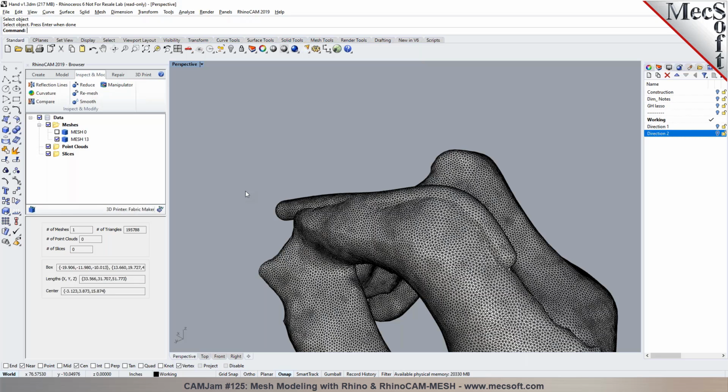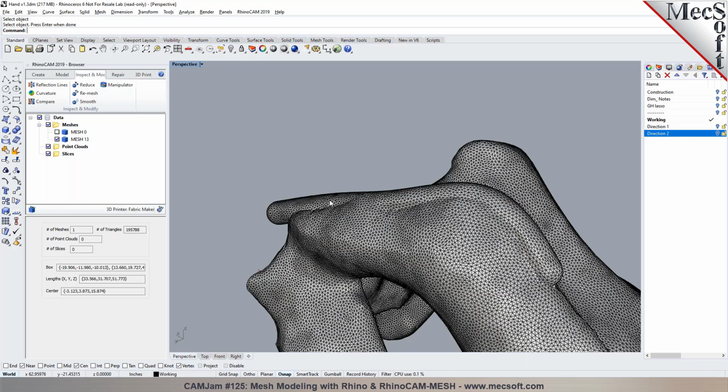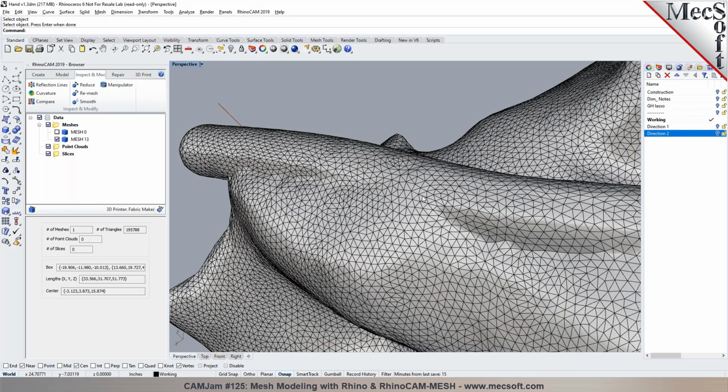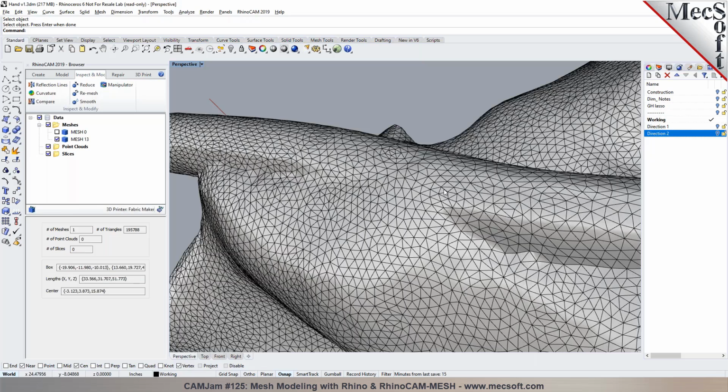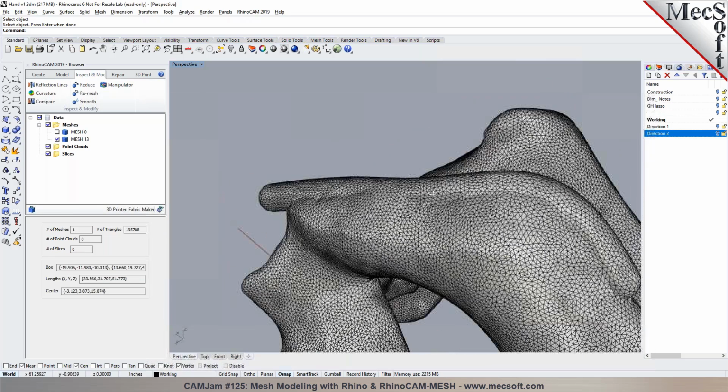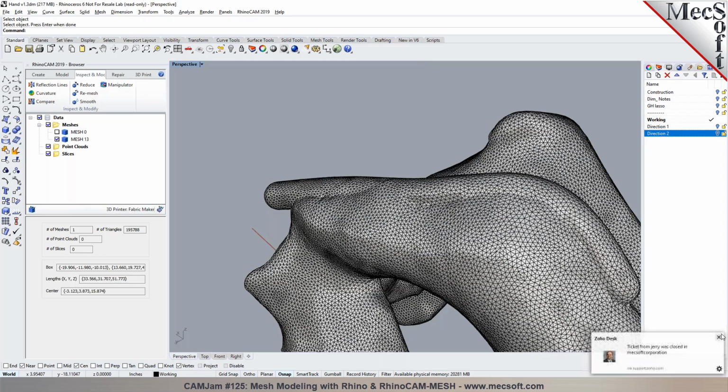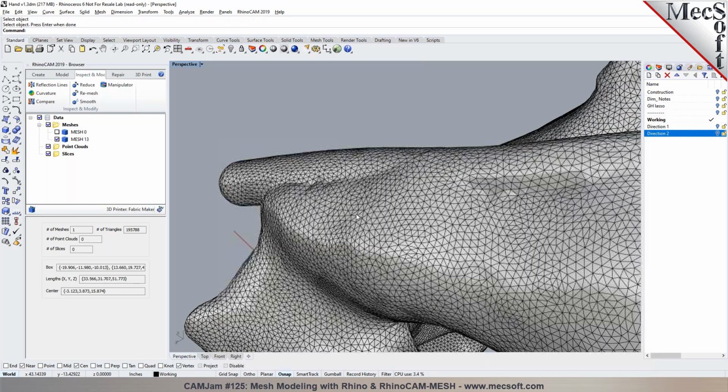Right. Those are certain things you can probably look into. One of the things I'm doing with my other scanner is scanning stairways, for example, or framing of a house so we can put a stairway in there. And I want to be able to pull dimensions, but if it's just a point cloud, you really can't tell what you're snapping to. It's millions of points. When you create a mesh from a point cloud, it becomes vertices, and you can use the point snap to snap to it. But when you have millions of points on top of each other, you don't really know what you're snapping to.